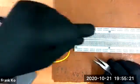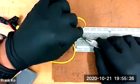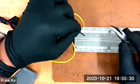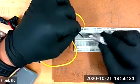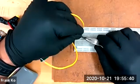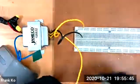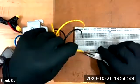That's one. Put the center on anything here again. Don't shove in with the wire. If you shove in with the wire, you'll break a certain aspect of the tinning. Rather, grab the tinned end with your needle nose and gently guide it, start it into a tie point hole. There we go. And then the third one, let's go to a bus rail here.